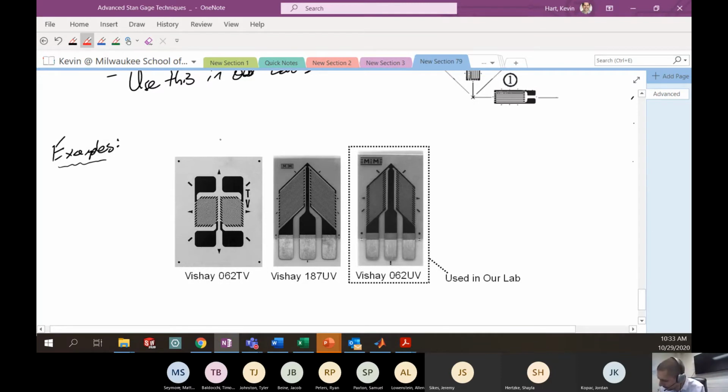Okay. So if we think about this as, here's axis number 1, here's axis number 2, and we call this X, Y. Or maybe it's easier to go the other way. Call this X, Y. Then we see that this particular gauge here has all these resistors that are moving in this pattern, which is at 45 degrees with the x-axis. The other gauge here, which is gauge number 2, has its resistor moving in this way.